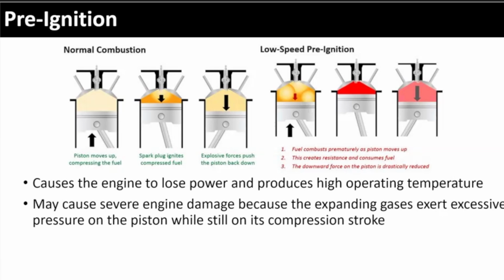They're just not throwing the right signal for the right spark. And you'll know if this is happening: it's not going to sound right, it's not going to feel right, it's going to be rough. If your engine's running rough for one reason or another, whether it's detonation or pre-ignition, it's a good idea to have somebody look at it.